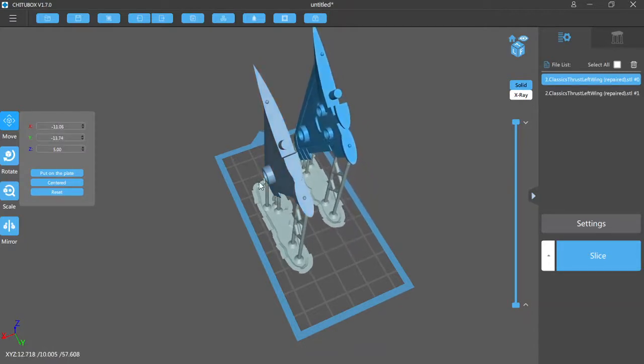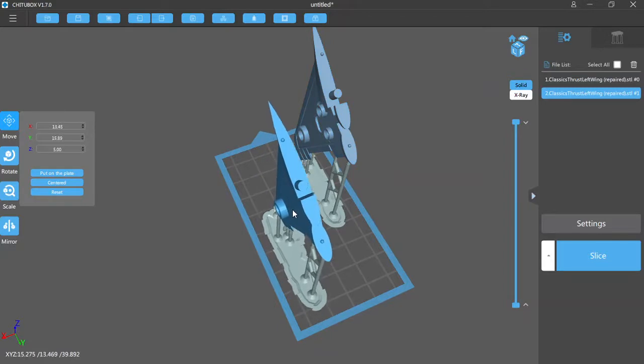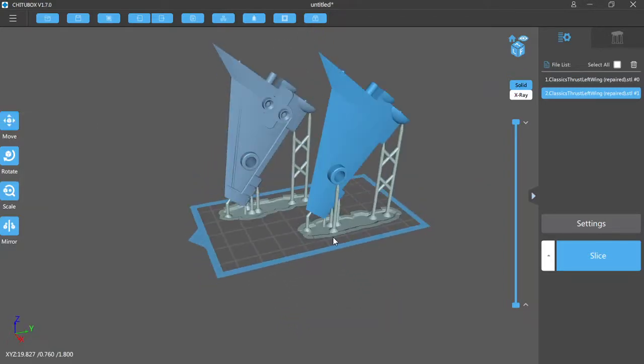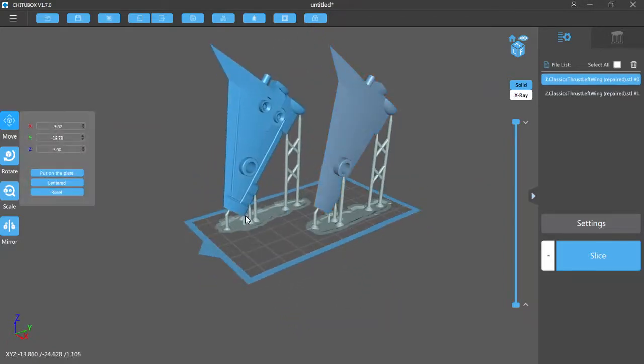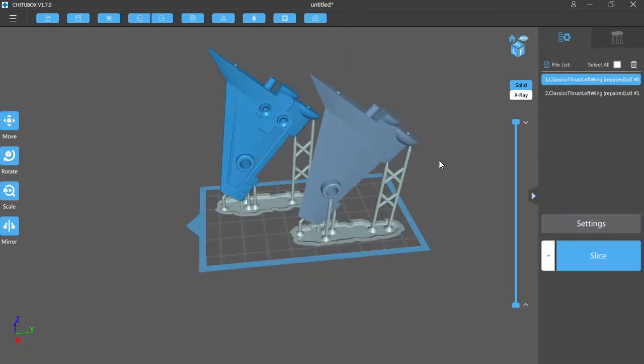Now sometimes what I'll do is try to separate them out, split them enough on the bed that they're not going to make a really hard force. But sometimes you'll listen to it and you'll hear it moving up and down, and it will pop slightly, which means it's probably sticking too much to the FEP.